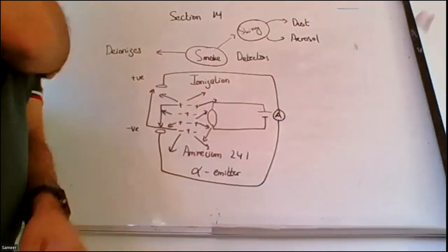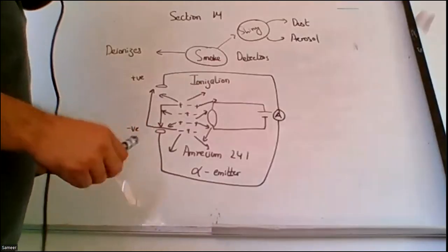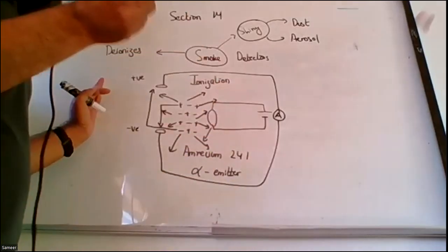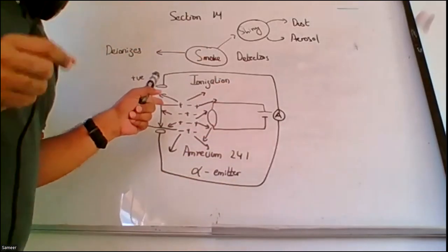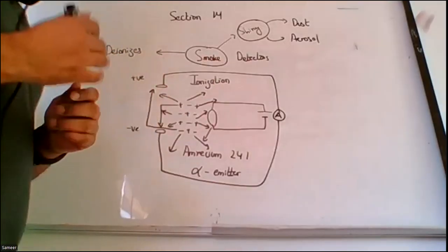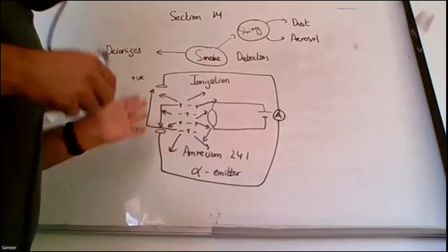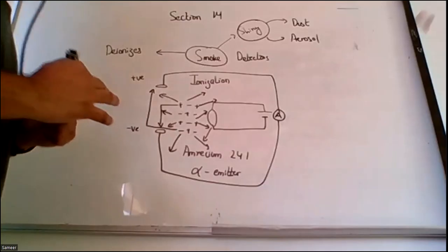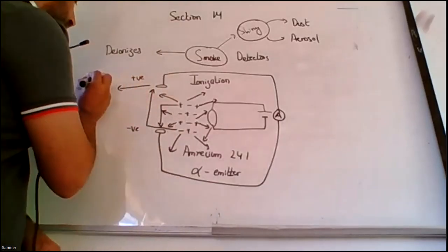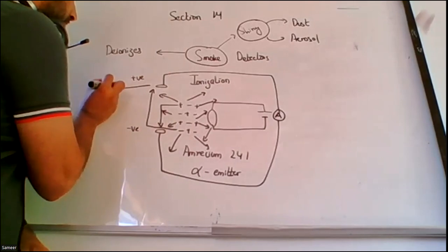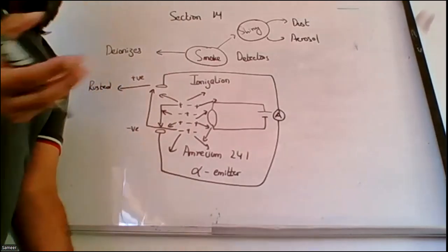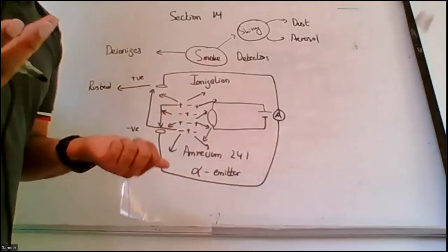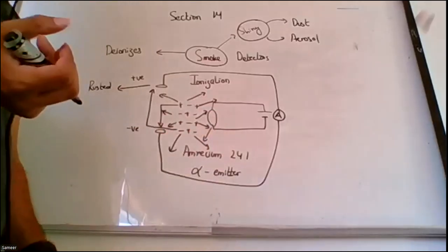Similarly, if I discuss the ionization detectors, through understanding the whole process, the only way I can trigger an alarm is the discontinuity of the electric current. This electric current can be discontinued for various reasons other than the smoke itself. For example, if your charge plate becomes rusted, it has lost its integrity. Negative particles will not be attracted towards the positive, and the current will discontinue. So your alarm will trigger.